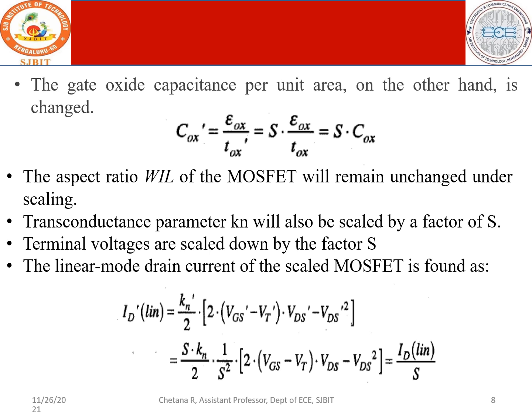Tox dash is Tox divided by S, so the denominator S will come to the numerator. Therefore, you have the expression S dot epsilon Ox divided by Tox. Epsilon Ox by Tox is nothing but Cox. So Cox dash is equal to S into Cox. This is one important formula you need to remember, along with the original previous dimensions which I have already told you.